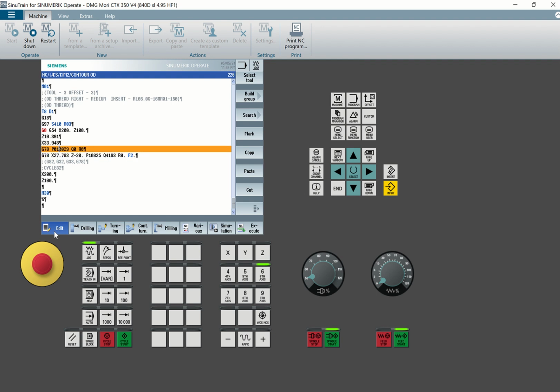So I will show you how to write this program. You can use it for this code to accept. You can start from here. Let me show you the simplest. You can use G32. From G32, you want it to go to a depth of, let's say, 30. So 30 minus 0.8, so we are getting 29.2, that is X29.2.